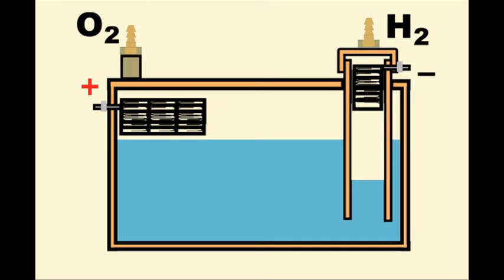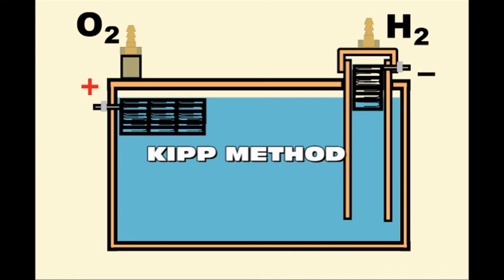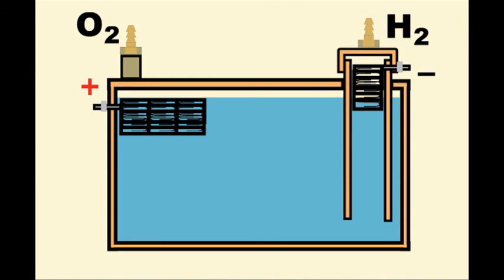Although not included in the drawing, there is an automatic water feeder to be replenishing the water used up during electrolysis. This cell can produce hydrogen in a practically uninterrupted way, with safety control at all times by preventing the gases from mixing. This control method of chemical and electrolytic reactions works on the basis of the Kipp generator, which was widely used in the past in all acetylene generators for the so-called oxyacetylene welding.